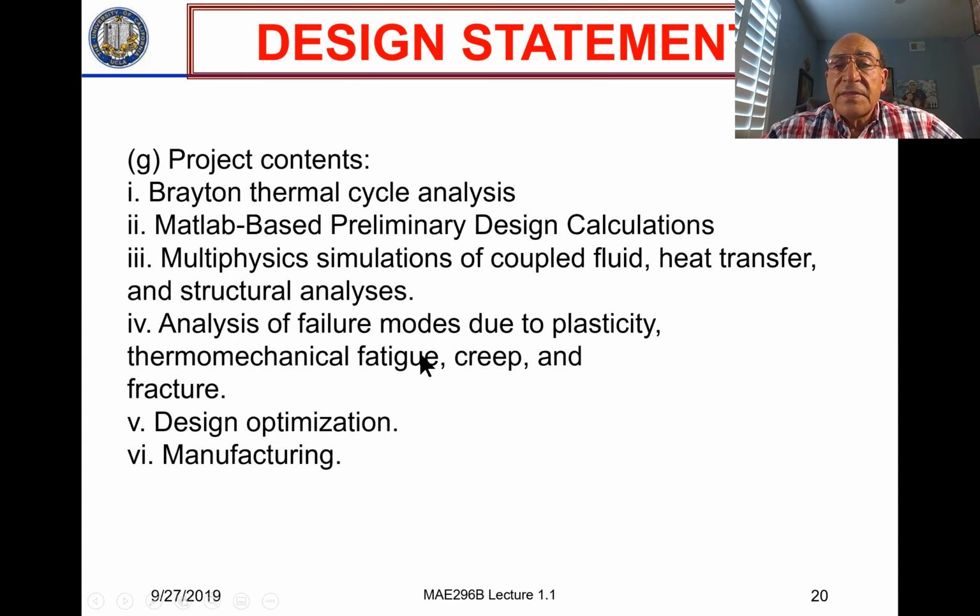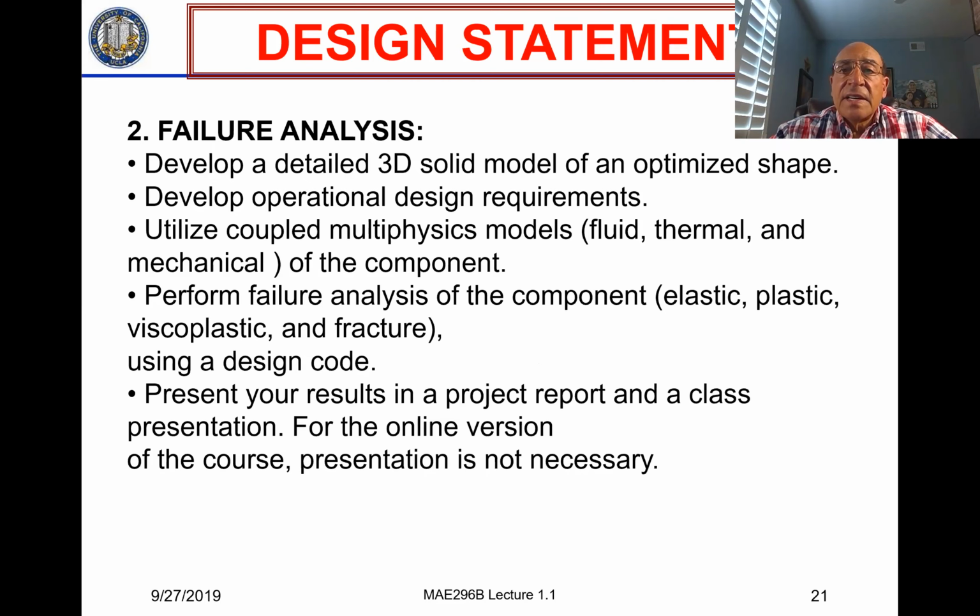And then you analyze the failure modes due to the three topics that we mentioned in the course: plasticity, then time-dependent phenomena like fatigue and creep, and then finally fracture. As you come towards the end of the course, your objective would be to define a few geometric parameters that you will vary to optimize your design and achieve the effectiveness that is required. We would like to have an effectiveness for this design of 80% or greater. Very, very challenging.